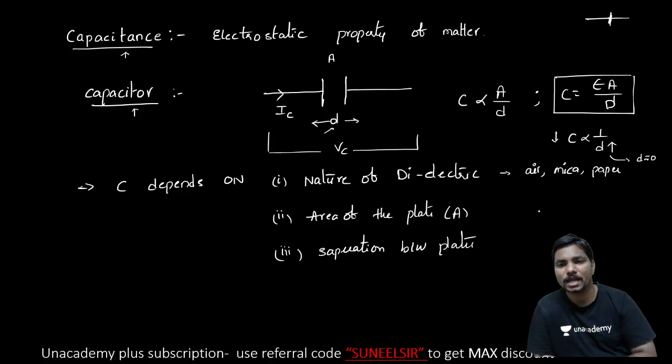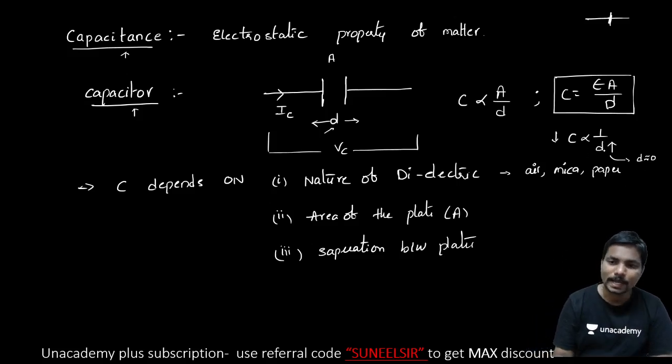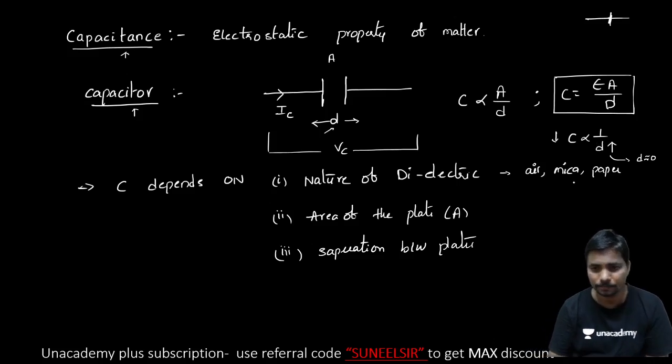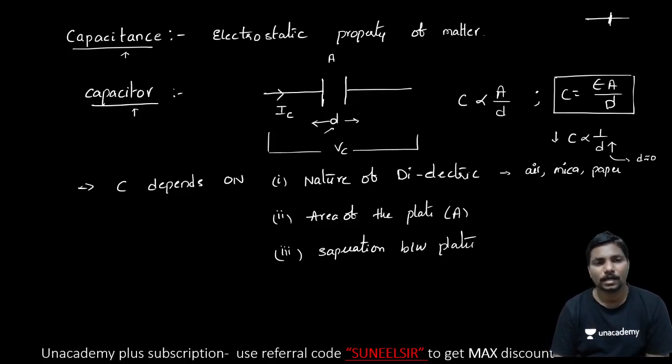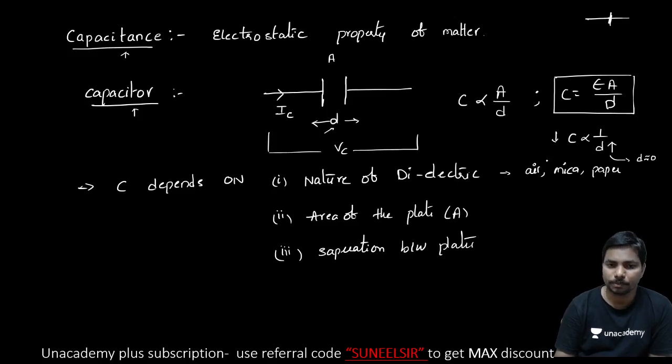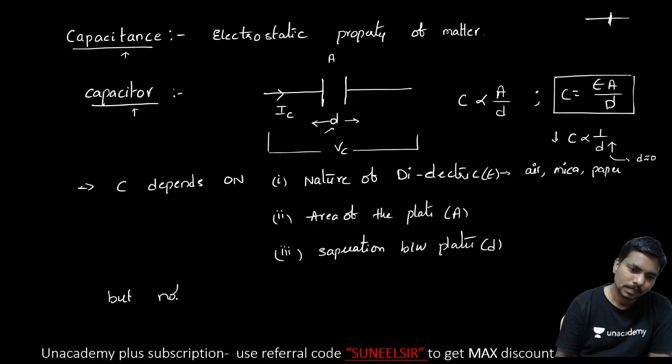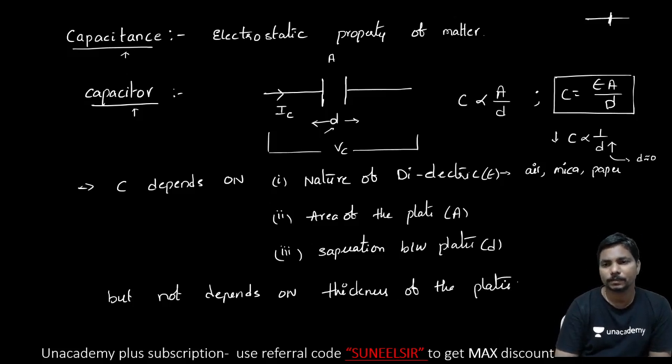I think many students have a doubt on this. So don't think that as the distance is zero, capacitance is infinity. As the distance is zero, it does not belong to a capacitor. It may not have the capacitance, it may not have the storage property. So capacitance depends on nature of dielectric, area of the plates, and separation between the plates, but does not depend on the thickness of the plates. Very important question. It does not depend upon the thickness of the plates.